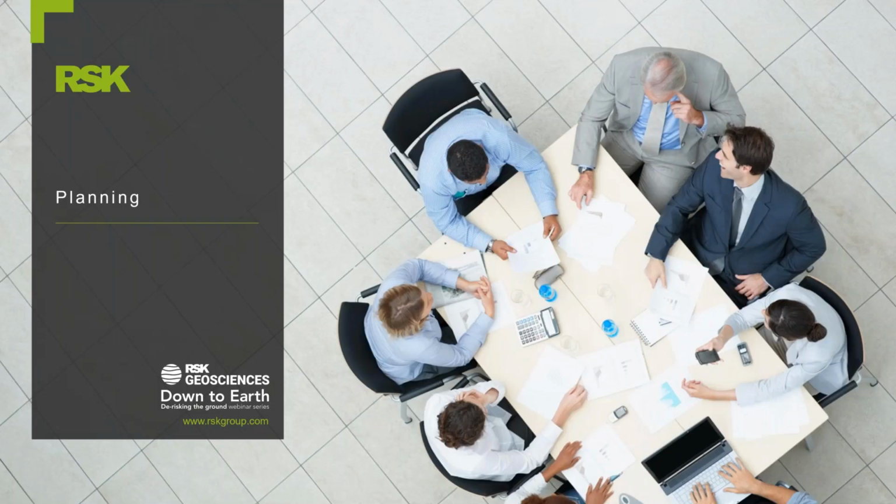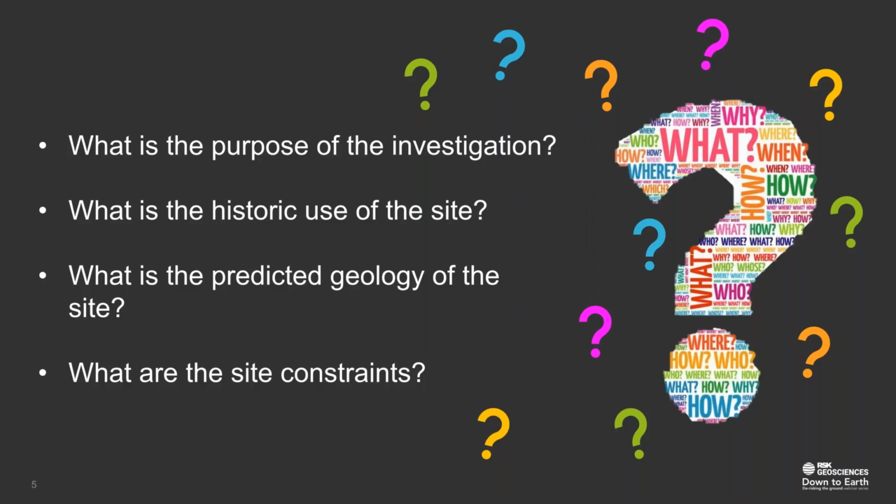Step 1 is always planning, and it's probably the most crucial step in the whole process. But to start this planning, we need to ask ourselves a few questions. What is the purpose of the investigation? What is the historic use of the site? What is the predicted geology at the site? And what are the site constraints? Now we're going to go through each of those in a bit more detail.